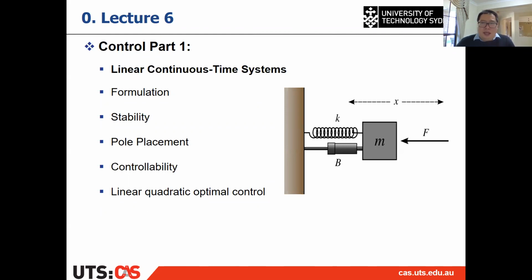The pole placement is you first use the state feedback control. Then you change your system from Ax plus Bu to A minus BK x. Right? And you can choose a proper K to make A minus BK have all the eigenvalues negative. Then the new system is stable. Right? But not all systems allow this kind of pole placement.